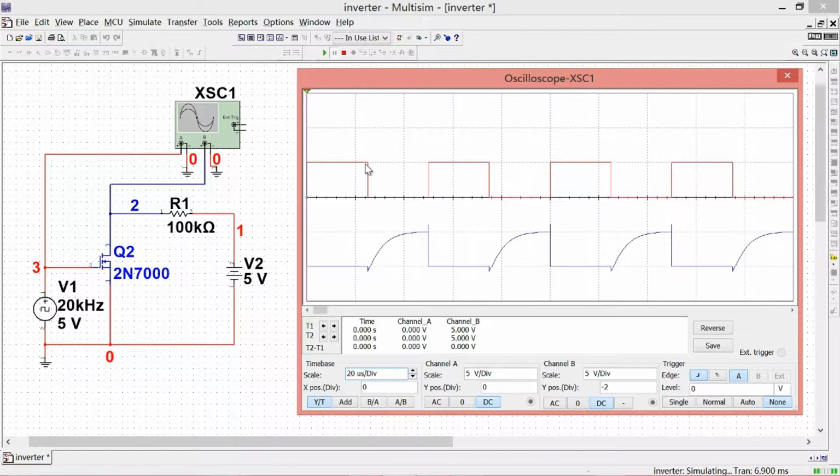When the input signal is 5 volt high level, the output is basically 0 volt low level. The logic is correct. However, when the input signal is 0 volt low level, the output is not satisfying 5 volts high level. It means the inverter reaches its maximum operating frequency. When the input signal's frequency is beyond its maximum operating frequency, the result of the logic operation may be wrong.